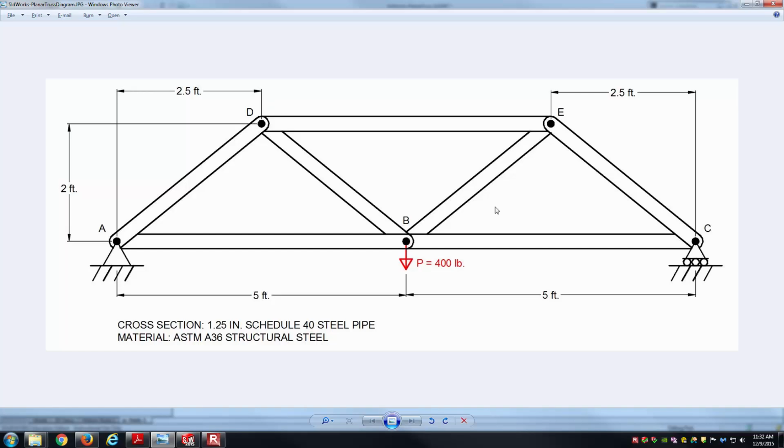Well, inside of the plane, they're going to move a little bit, right? This truss is not going to be rigid. It's going to go through some deformations. And so we want these things to be able to slide around inside the plane just as they would. And that sliding around is going to be controlled by things like the stiffness of the members there, the material we make them out of, the different cross sections and so forth.